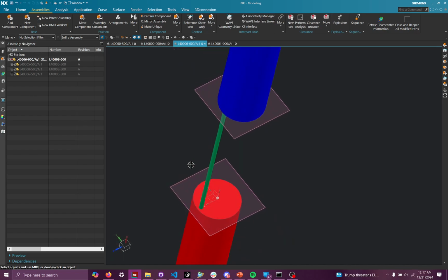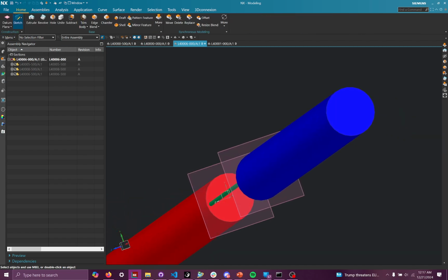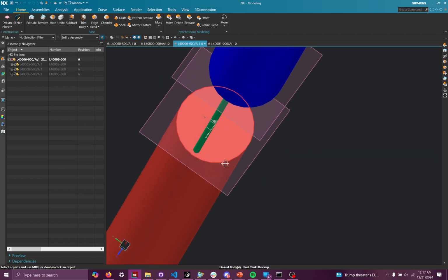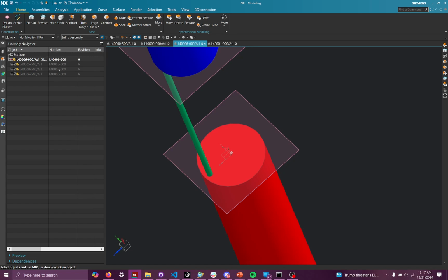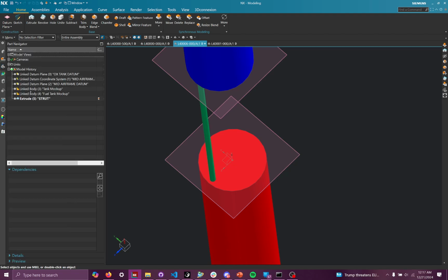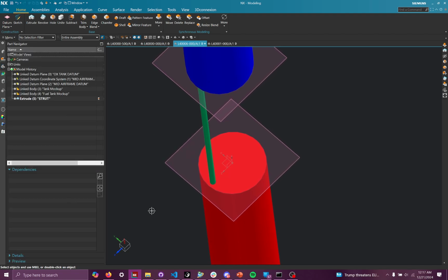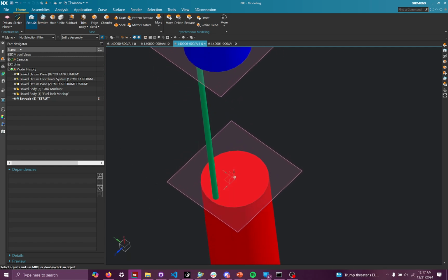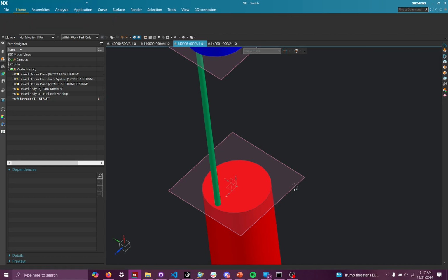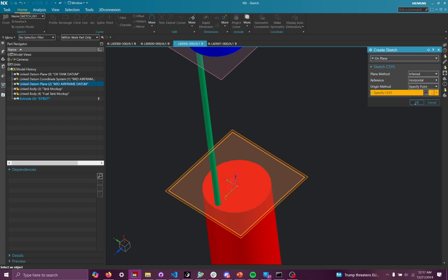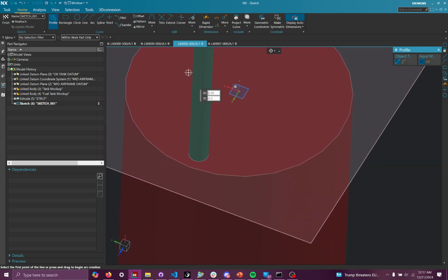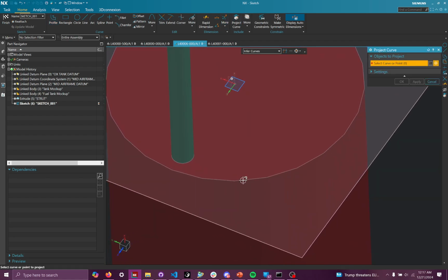So we have a strut here. We probably also want some kind of paneling to keep the aerodynamics of the rocket efficient, or keep stuff in, whatever your reasoning is. So let's actually make that part. I'm now within the layout file for mid-airframe, which means I can do modeling in here. So let's do that. I'm going to use this datum, this lower datum, as my building off point, I guess, but I'm going to project curve.